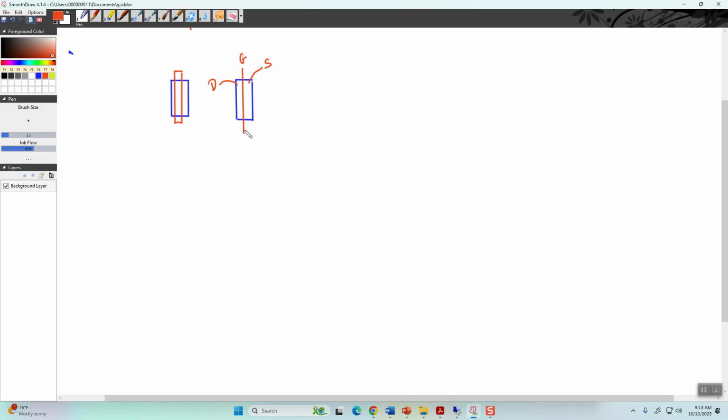So I don't need to draw it out. Unless, for some of the NMOS things we'll do, the length will be longer. But really, we're concerned with the width. And then this overlap, depth of drain, is really controlled by the contact and the design rules to make sure that this is manufacturable.